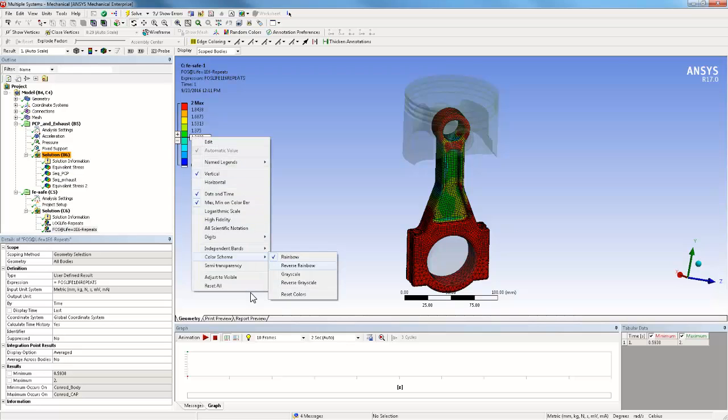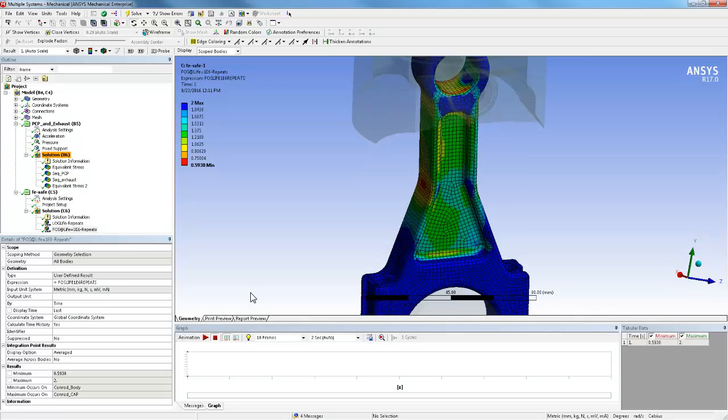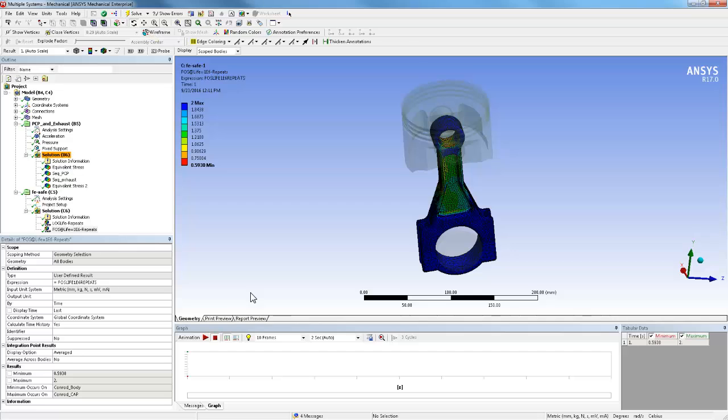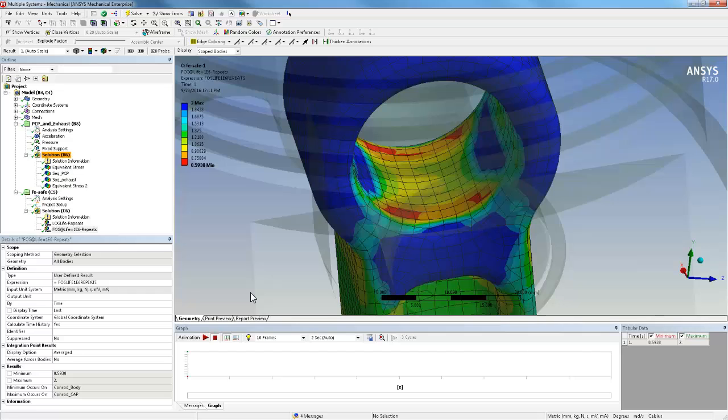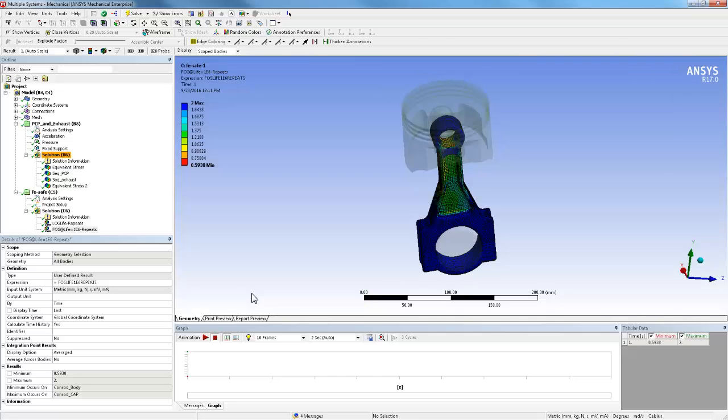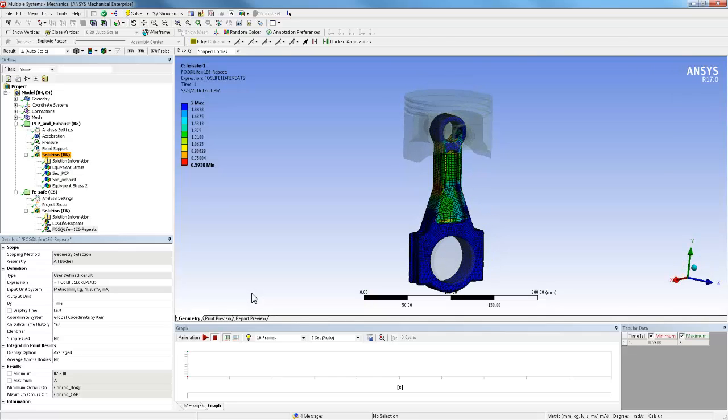So this example might have demonstrated how basically you can directly take advantage of the ANSYS Workbench plugin in order to run simple workflows. But if you have a complicated workflow, then definitely you can use the advanced setup, go to FE-SAFE, run, consider your loading and materials which you want to use for your complicated workflow, and then come back to ANSYS Workbench and run again. Thank you.